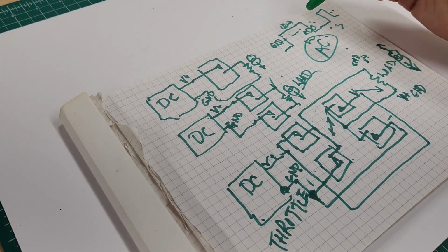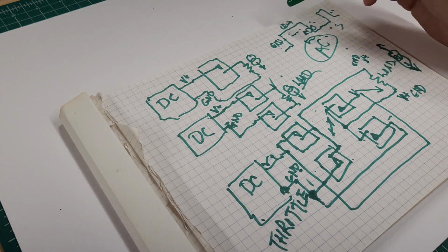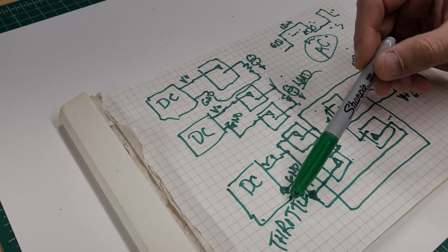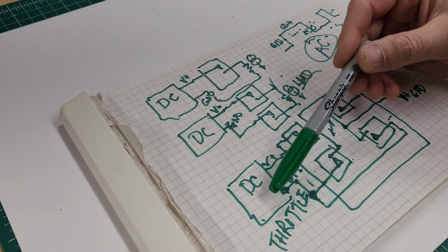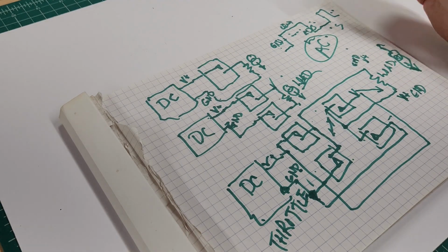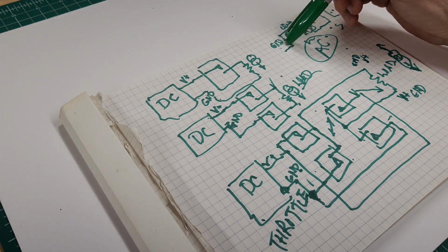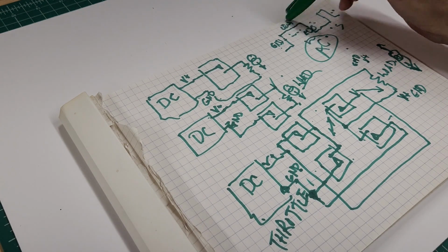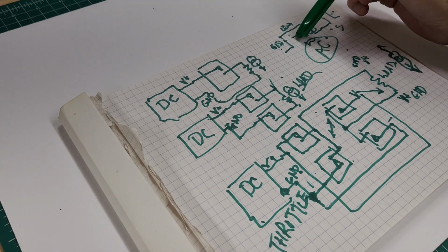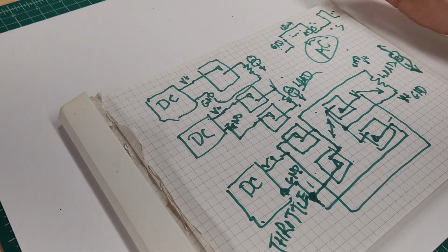Given that, the question then is, now that this signal is applied, it doesn't come with a ground reference, it's just floating. So it floats with respect to the throttle. And the throttle had its own ground from its own power supply, so that was not an issue. But with the decoder, it becomes sort of an issue, and it has to figure out how to extract these coded durations that indicate the zeros and ones, but it also has to be able to convert this signal into a DC source that can power up the decoder to begin with.